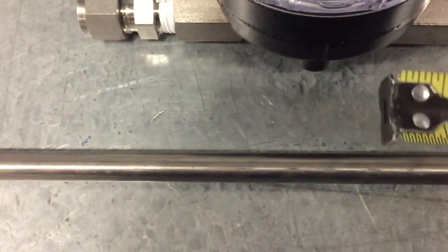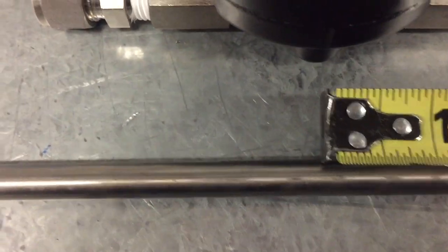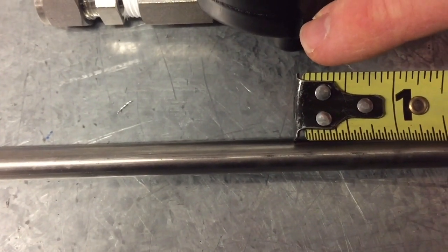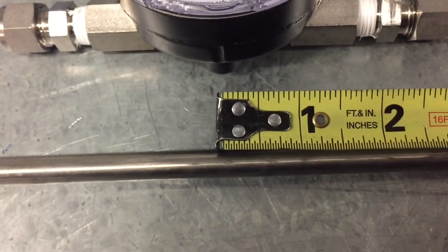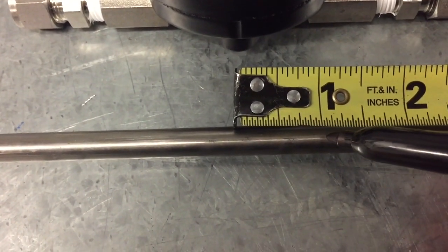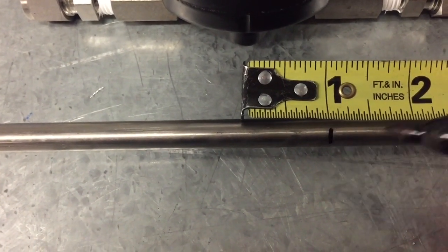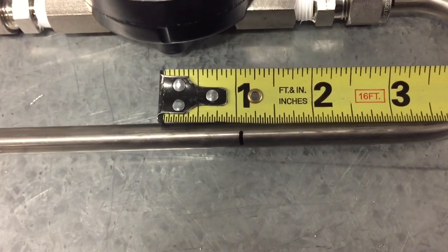And what I want to do now is position the tape measure at about the center of the gauge. So right about there, or about center. This little mark here on the gauge is the center of it. And we're going to bend it at 90 down into that top fitting on the manifold at about an inch and a 1/16. We're just past an inch there. So we'll mark that so we know where to bend our 90 degree bend. And then we'll go ahead and make the bend.